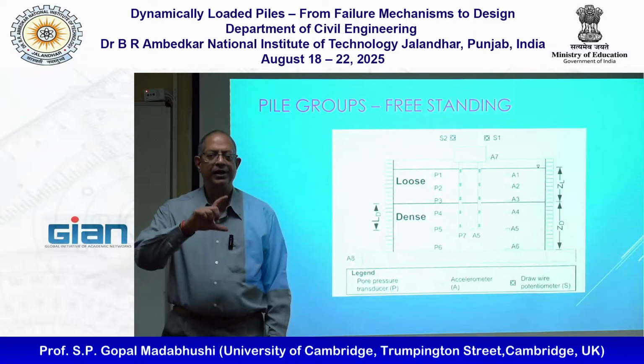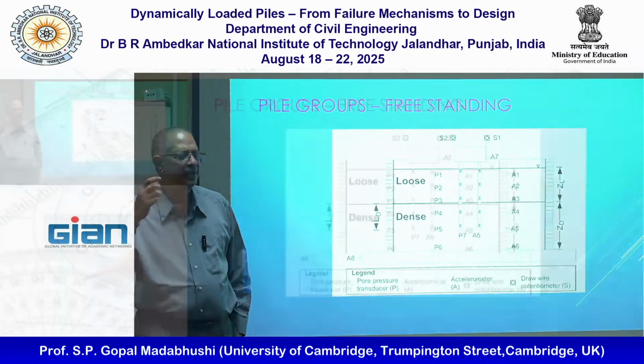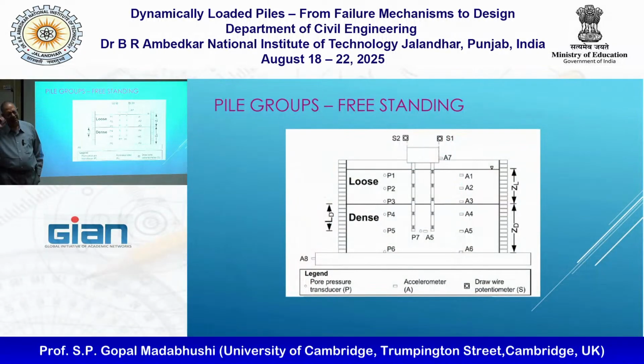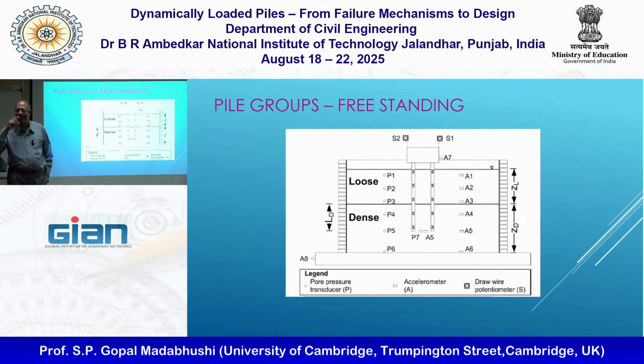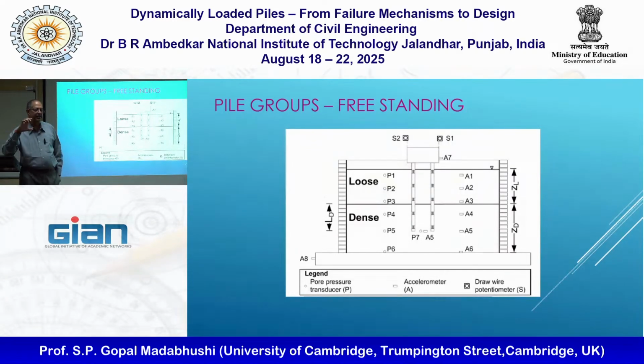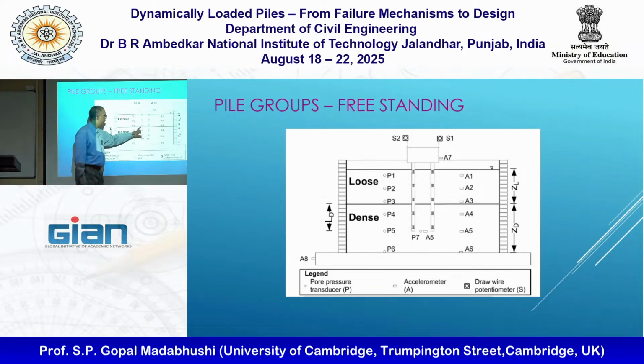Normally, you work out the effective length you need by using, I think, Bond has one equation, Fleming has another equation that tells you how deep I should go, maybe 5 pile diameters, or 8 pile diameters into the dense sand. So we followed those rules and installed them to that depth.